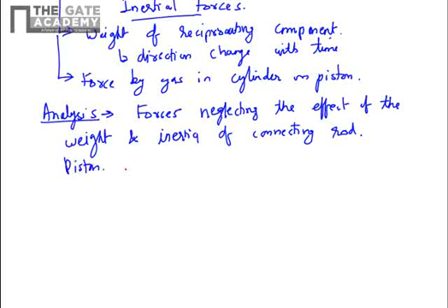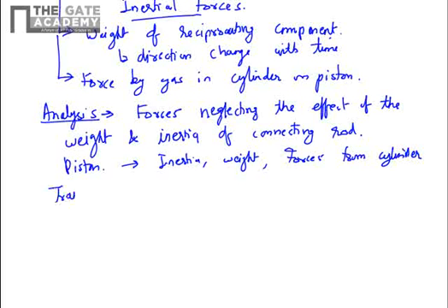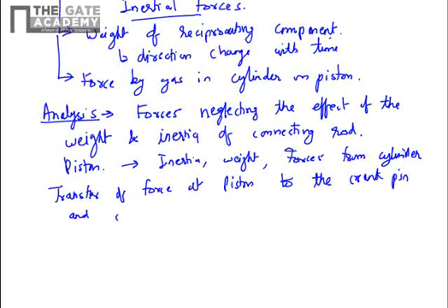Basically, we will consider the mass of the piston, the inertia of the piston, weight, and forces from the cylinder, and how this force is transferred at piston to the crank pin and crank and connecting rod.